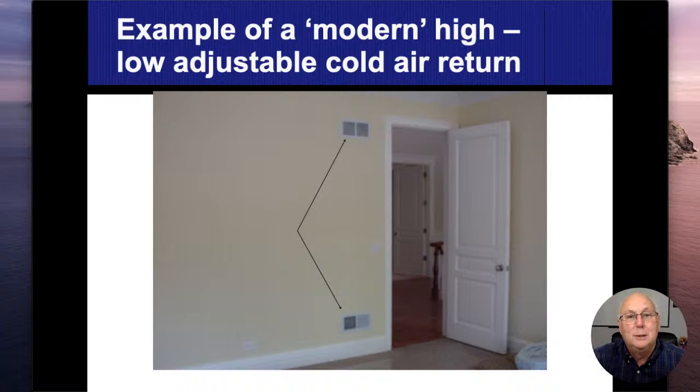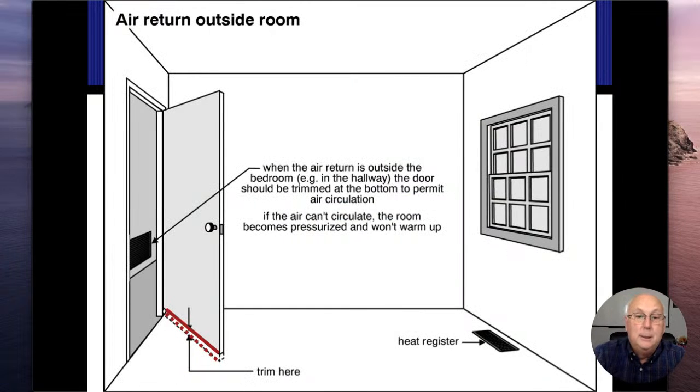So as we're showing on this drawing here, the grill is on top, the register is on the bottom. When it's in heat mode or the furnace is running heat, we want that register on the bottom open, so the damper open. And when we're running in air conditioning mode, we want to take it from the top, so we close the damper. We're going to run into houses also that have a central return still. Most of the time that's where we're going to find our filter. So we want to show our clients how to open it and change it. If they know already, that's great. If they don't, they're going to want to learn.